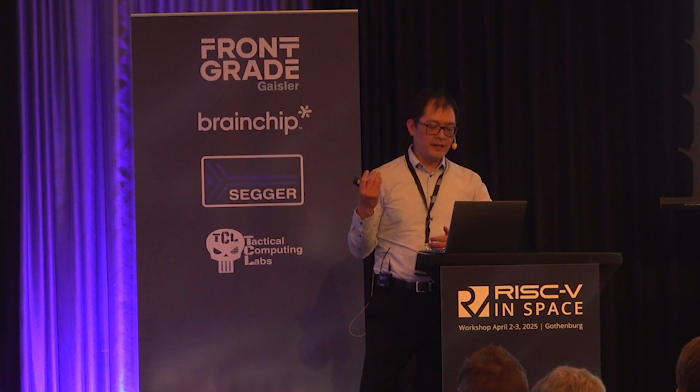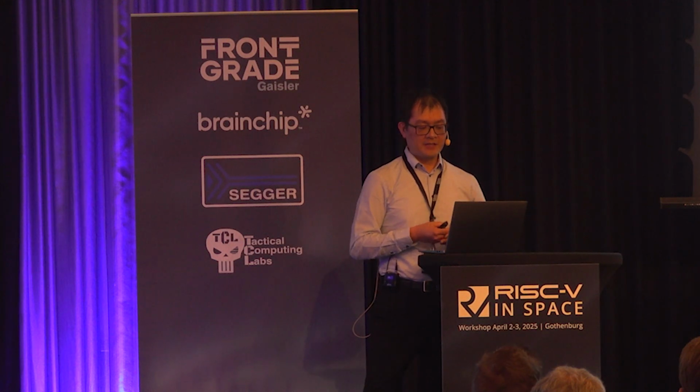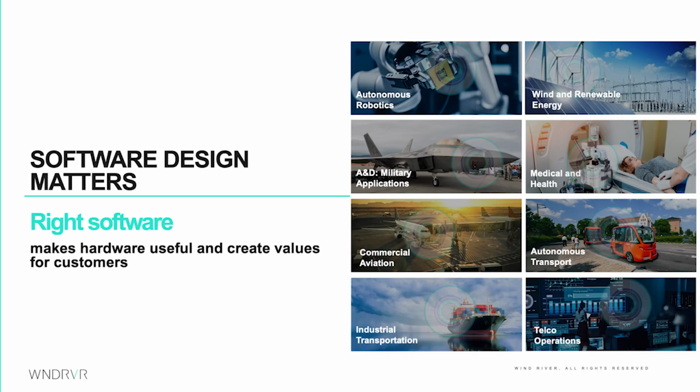Within the embedded and space sector, the RISC-V architecture gives us significant opportunity as well as challenges, because its defining characteristic is that it is very extensible and very customizable. The freedom that gives us through unique instructions and configuration parameters is both very exciting and terrifying.